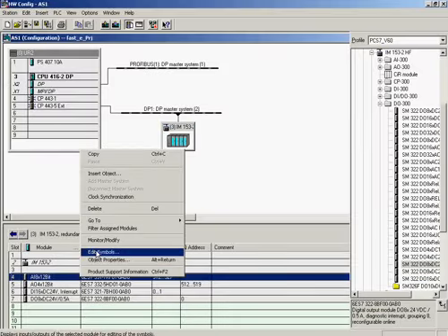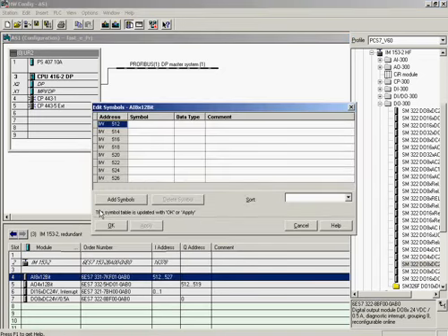The Edit Symbols dialog is activated to enter the symbols. The symbol name PVIN of controller 1 is entered in the first line as well as in the comment column. This is done by copying the symbol name to the clipboard and pasting it into the comment field. The corresponding symbol name of controller 2 is entered in the second line as well as in the comment column.